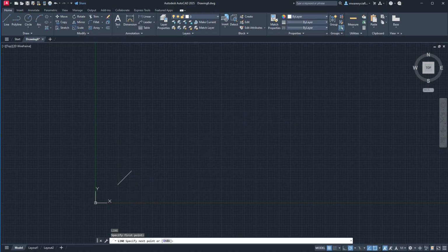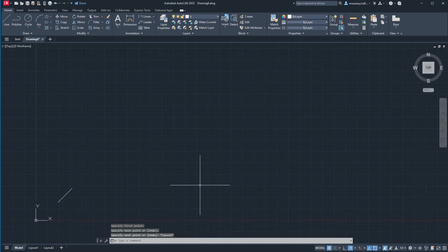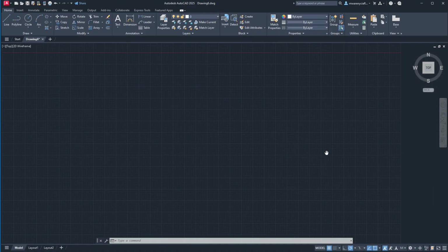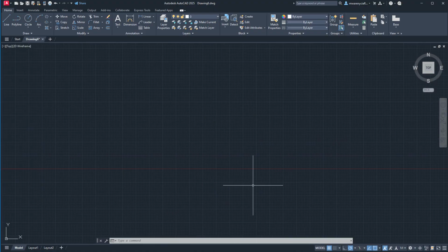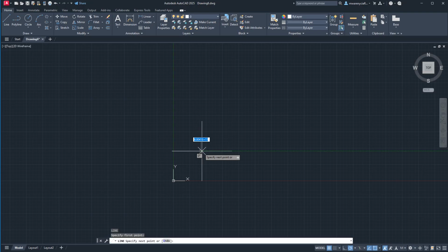Another option, I'm just going to draw a line here, we'll talk about that in a second, is to zoom extents. Occasionally something weird will happen, and I've seen people glitch way out here where they can't see their project, and then I check and a line that long is bigger than the earth or something, right? So zoom extents is a great way to fix that.